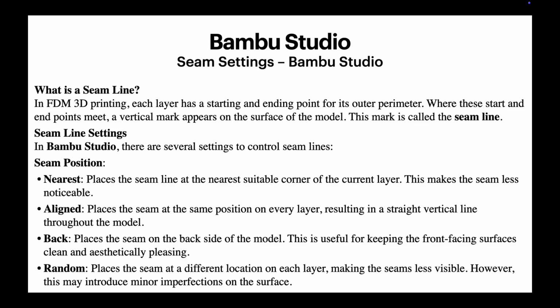Seam settings: controlling stitch lines. Hello. In this video, we'll talk about what seam lines are, those vertical marks you see on the surface of your 3D prints, and how to control them using Bambu Studio. Especially for aesthetic prints, understanding these settings can make a big difference.